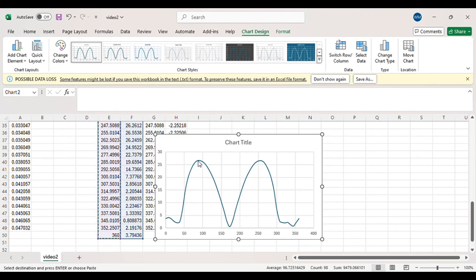After reaching its maximum value, velocity decreases significantly as it traverses the surface of the cylinder, reaching a minimum value at approximately the 180 degree mark. Looks like it happens a little before that, but theoretically it should happen at the 180 degree mark, since this is also a stagnation point. The curve repeats itself as it traverses the bottom of the cylinder, reaching a maximum value, which corresponds to the first one, at approximately 270 degrees. This corresponds to the bottom of the cylinder, where velocity is also maximized.